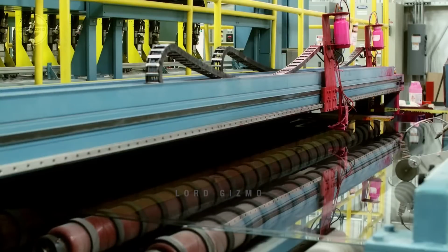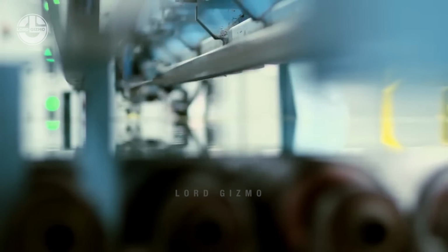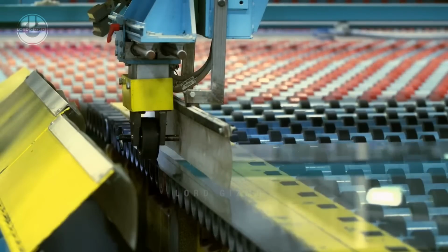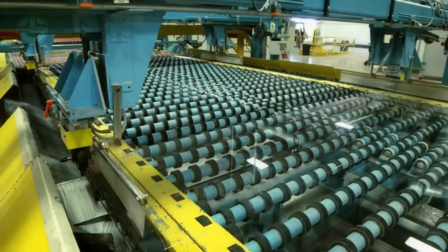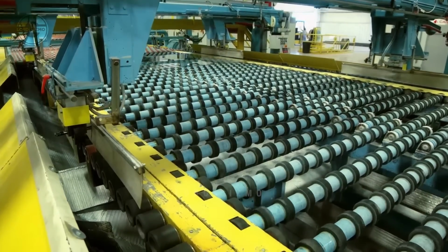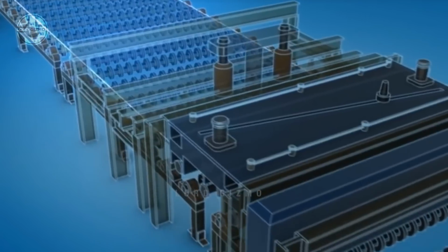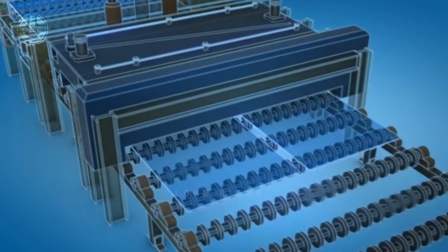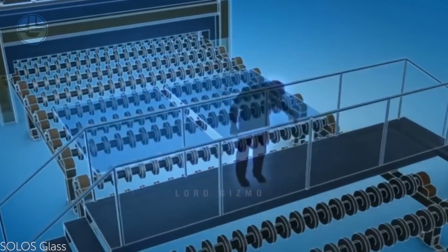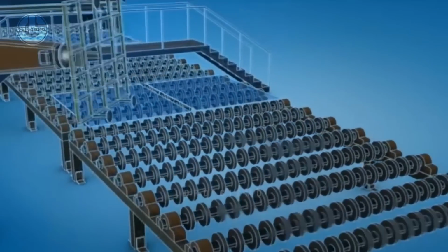A special device, the XY cutter, marks a thin, continuous scratch from one end to the other edge on the surface of the glass. This process is known as scoring, which offers controlled glass fracturing along predetermined lines. While going through a bump roll, the scored ribbon splits apart or is cut into pieces of glass sheets. The edges are then trimmed.